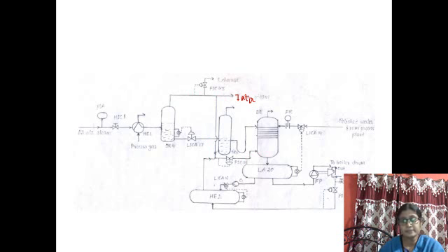Now the separated water in the separator chamber SR4 is then reutilized. This is nothing but water, so it is reutilized through another separator unit. Some pressure still exists within this, so that will be released here, open to atmosphere, and the water is then sprayed from the upper edge of the deaerator unit.